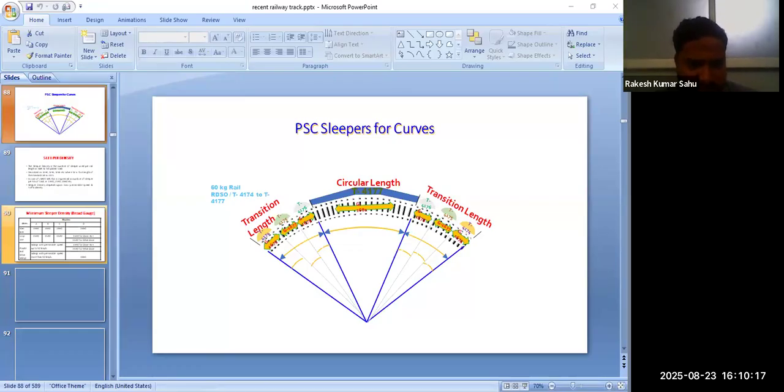So this fastening should be able to withstand lateral forces without any axis lateral movement or gauge retraction. Means our gauge would be uniform. That type of fastening we use in Indian Railways. So rail fastening transmits all the forces to the sleeper via a firm connection. If it is not possible, forces will increase to such an extent that the rail will overturn or the sleeper will be crushed. So this fastening is a very important part of track structure.